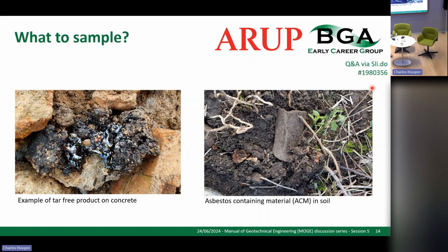So again, if you have taken these samples, you really need to remember what they are when it comes to scheduling. The other thing on scheduling is I've seen far too many times where we take a sample of this and see that asbestos sample get tested for things like TPH because the engineer has forgotten what that sample was and what was tested for. And you don't really want to be the one where the lab comes back and tells you that they cannot undertake that testing because it's just not appropriate.